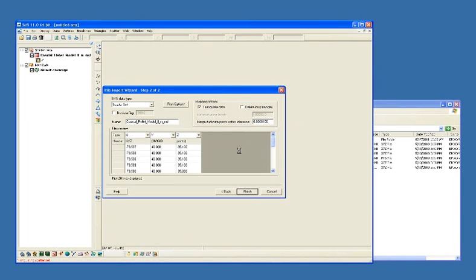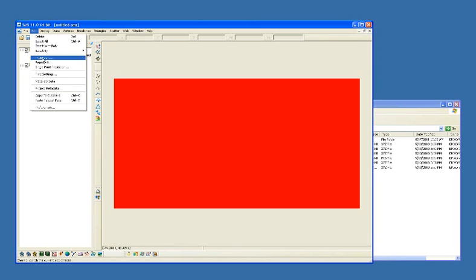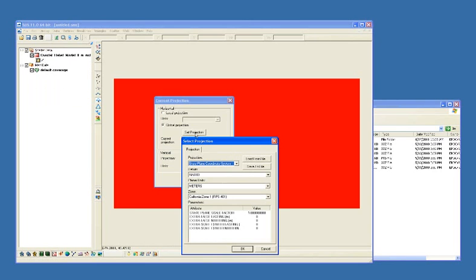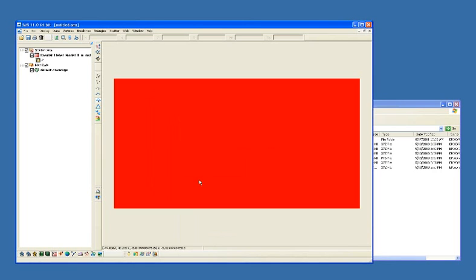All right, and so the first thing you want to do is to go in under Edit and set your general projection that you're going to be using for your grid. And so what we want this to be in is NAD 83 State Plane, New Jersey meters. So let me find New Jersey. All right, and that isn't changing anything yet. That's just setting the overall projection.